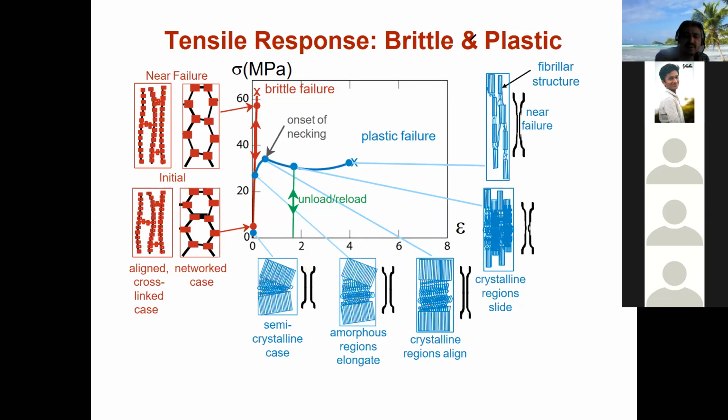Again, you are increasing the load, increasing the stress. Otherwise, what happens is that your material fails at the amorphous region. You will get failure in the amorphous region here. And your plasticity increases, your necking starts, and it collapses and goes near to fracture. That is at your tensile strength. Your material looks like this. All your amorphous chains break and finally your crystalline region is about to collapse. That is, you'll have a fibrillar structure here.